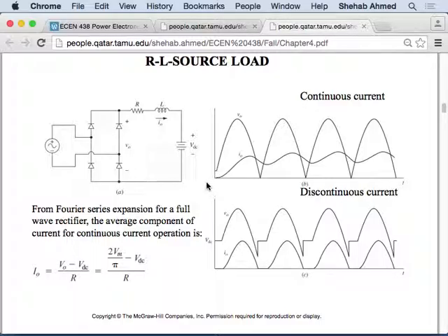So if I decrease VDC or increase L, I have similar effects, right? If I increase L, I'm forcing the current to change slowly. Or if I'm decreasing VDC, here they brought VDC down to a very low level versus a very high level here.